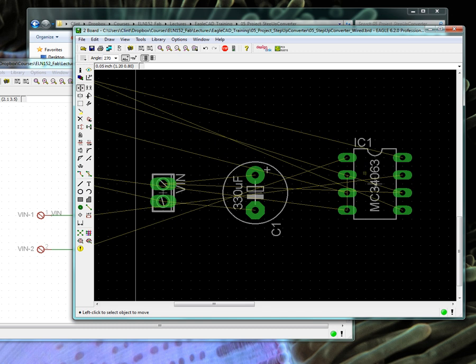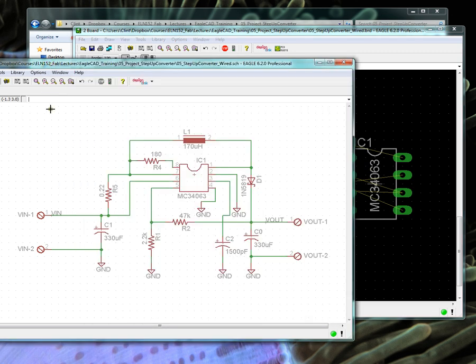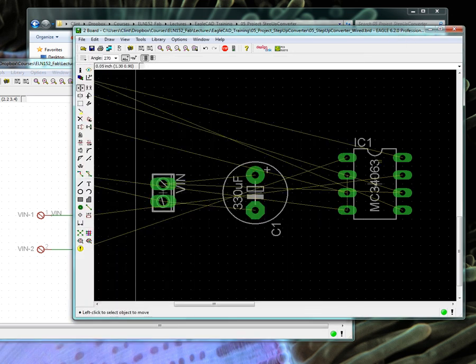But the problem is, I'm not going to get to have my wish here on this one, because by default these components, even though I've flipped it on my schematic, you can't really flip it in the design. These packages are designed so that if you look at this tab, and the tab is on the top, pin 1's always to the left. So it goes 1, 2, 3, 4, 5, 6, 7, 8. So you could rotate this part, but you couldn't mirror image it.